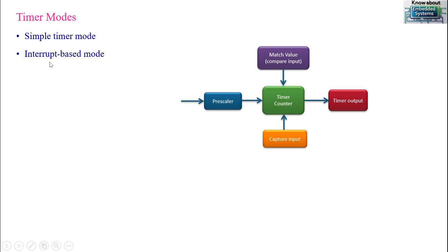Second one, interrupt based mode. You know that already. An interrupt can be generated in two different ways in the timer, one with a match value and one with a capture input. Both ways you can generate. So that is called interrupt based mode.